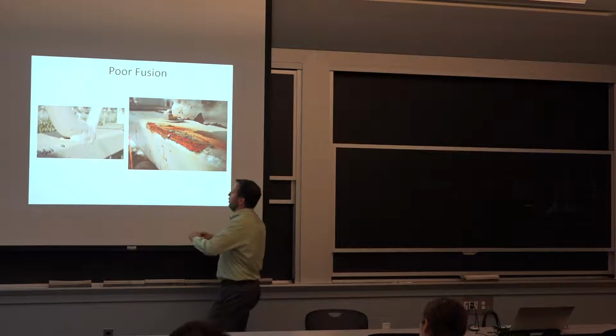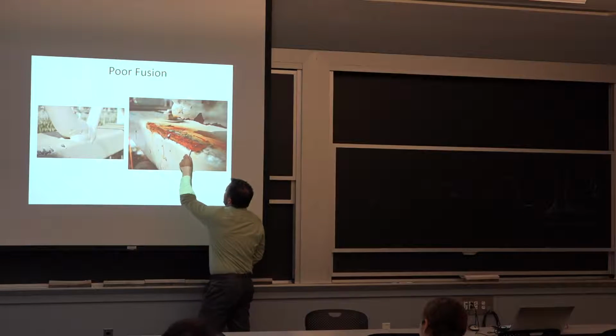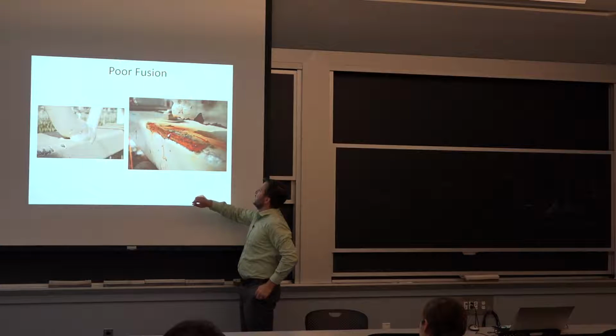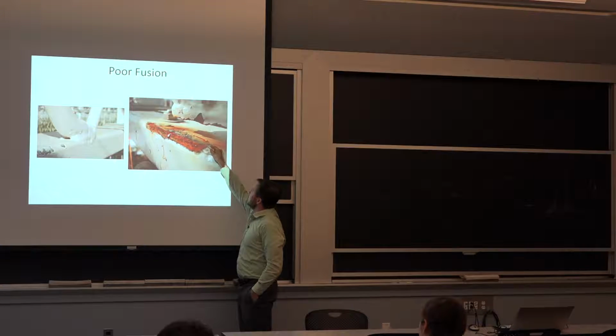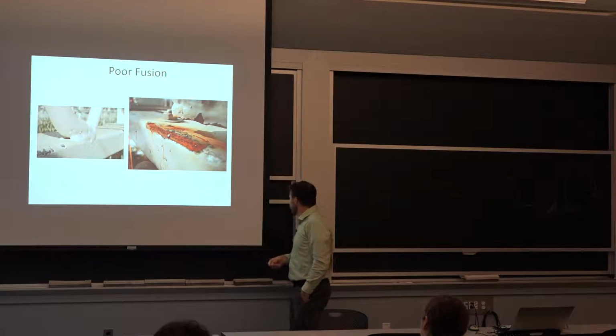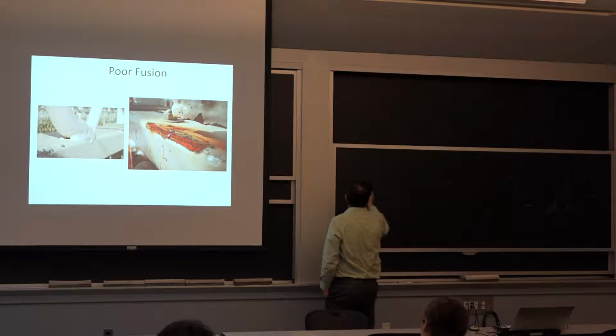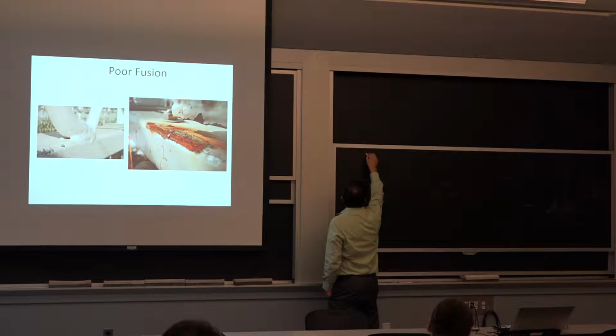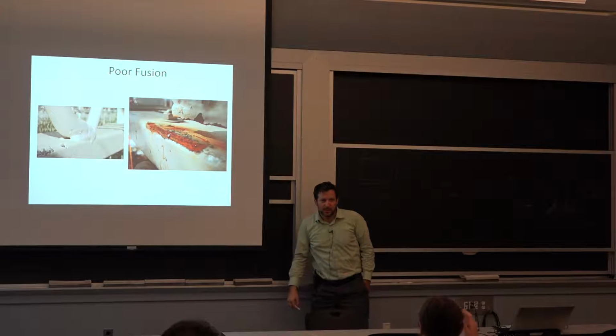So if we look at a joint like this, when it failed, the easiest way to identify the lack of fusion is this is the original shape of the tube. There's nothing that happened to it. So the tube is hollow, just like this, before and after. So the welding that was over here is just gone. And with the paint. Yes?